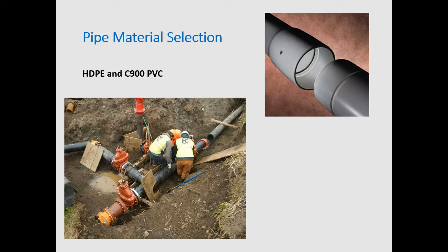Fine. So our recommendation is to use petroleum resistant gaskets in PVC, which is kind of what your upper right photo is showing. It's a bell and spigot. They use a spline, or in the other photo I had, where they put the little knobs in and hammer it in with a hammer. Either one of those systems is acceptable.